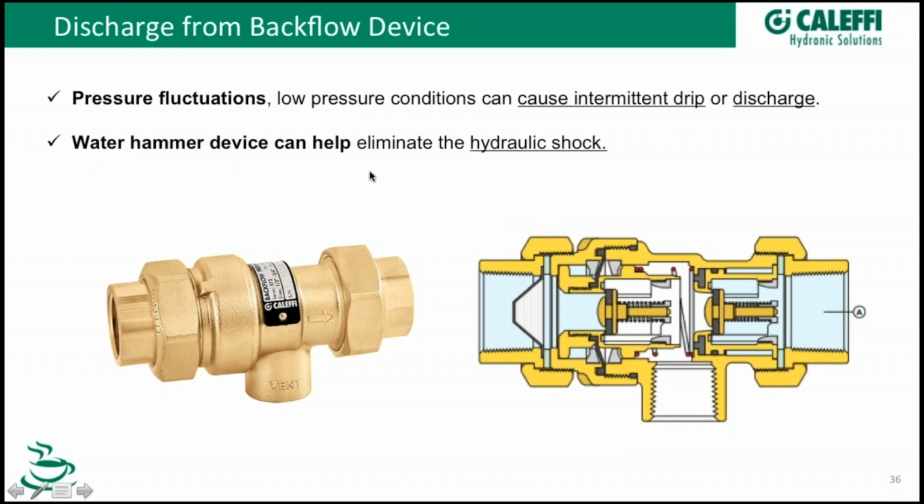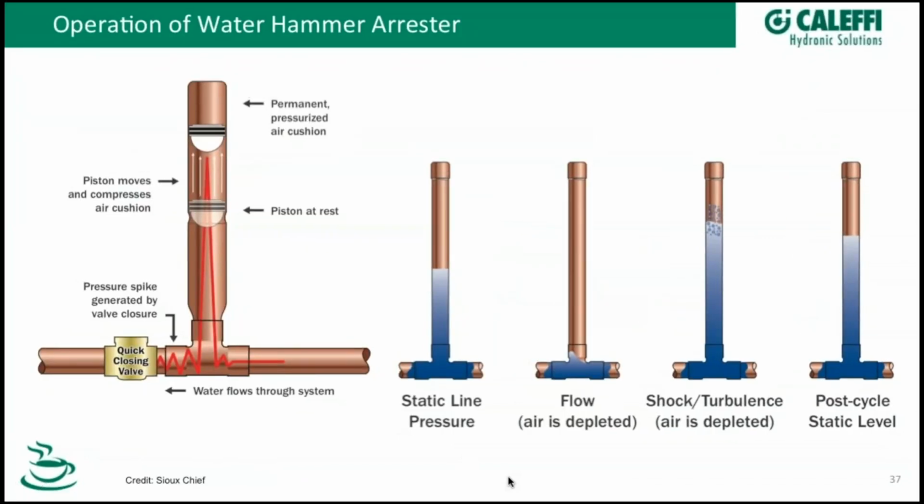Now, a water hammer arrestor can handle that. I know what some of the other plumbers do is they'll put an additional check valve right here upstream of this. So if you do have that shock wave, that first check valve, the swing check valve, will just clatter once or twice, dissipate that shock wave before it hammers your backflow preventer. So if you go and you're replacing backflow preventers on a job over and over and over again, it's probably not the backflow preventer. You probably got a water shock condition going in there.